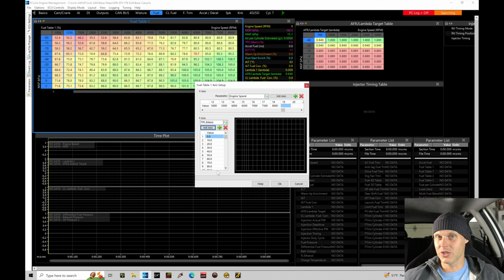Now, what we're going to do here is be very specific of how we set our breakpoints up. We need to have very fine breakpoints between 0 and about 12% throttle, because as we're giving it throttle input, the very small tip-in of throttle movement on big throttle bodies allows a pretty large airflow surge coming into the engine, especially at low engine speeds. So we need to be able to characterize that properly and give an adequate resolution in our table. We want to set up our breakpoint axes very specifically. Let me go in and demonstrate this real quick.